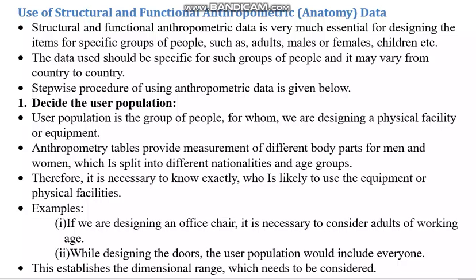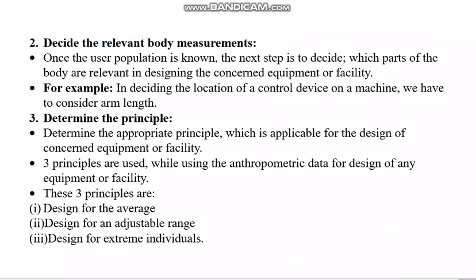That's why the height of doors in our country is around 7 feet, and the width is nowadays 4 feet. Whereas if you go to villages, they may not be so tall and so broad. This establishes the dimensional range which needs to be considered. Now, second is decide the relevant body measurements.